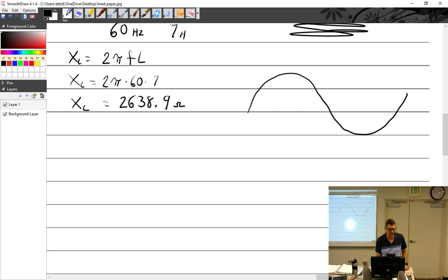This is a hard one. Voltage then would be way out of phase with the current. So the current would be up to 90 degrees out. So it starts way over here and goes up. And so it's now out of phase. So it's going to be like 0 over here. So it's 90 degrees out. So you don't want that. That is not an efficient circuit at all. And it's going to create heat and inefficiency, and it's bad.